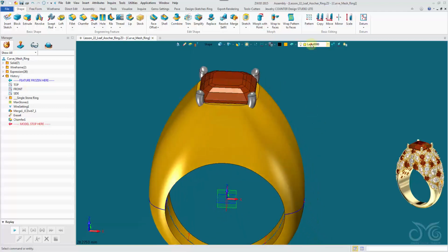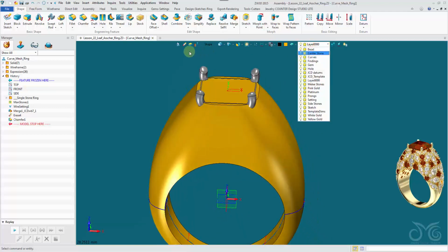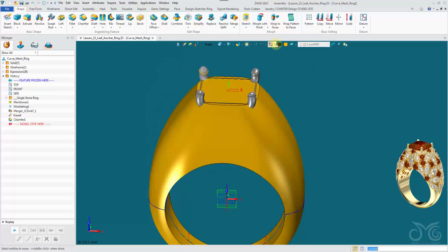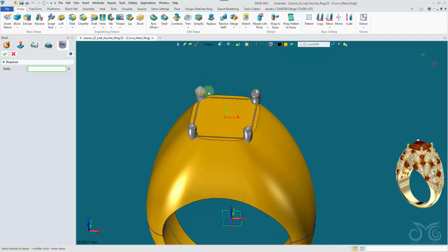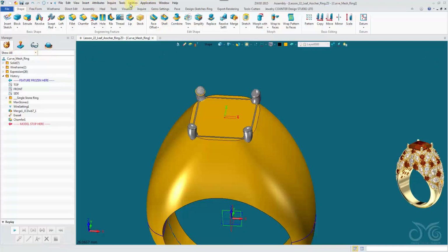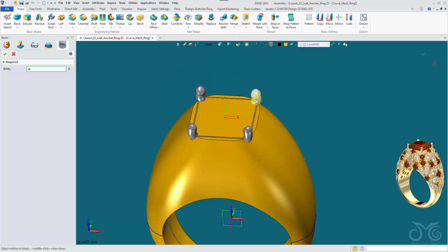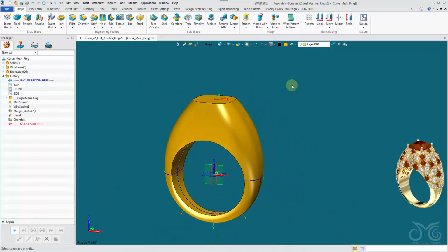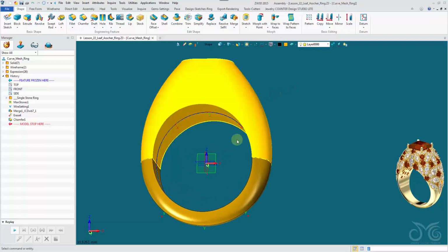Okay, I'm going to blank out that center stone, and I'll blank out my setting as well. Oops, I'm erasing, I don't want to be doing that. Blank. Let me unpick, unhighlight all, blank. Blanking out the setting, middle click. Okay, next up I want to come in and create the undercarriage, the piercework on the inside of the ring.